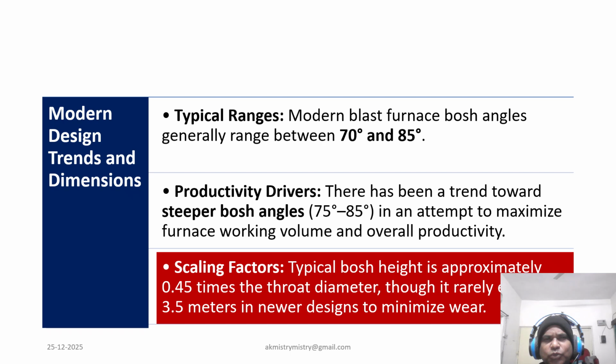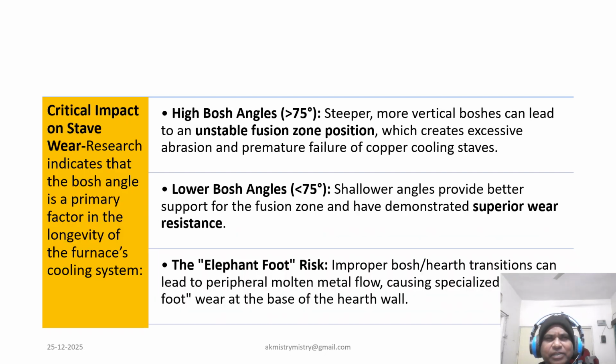So we need to trade off productivity versus campaign life. Designing a blast furnace is an exercise in balance. On one hand, you have productivity: a steep angle increases volume and output. On the other hand, you have campaign life. A shallower angle protects the refractory and cooling elements, with the goal of reaching a 20-year lifespan without a major reline.